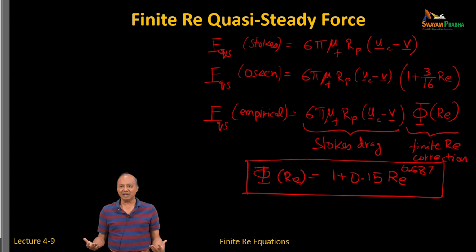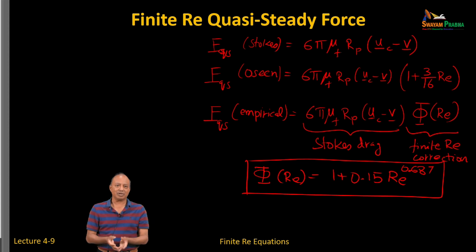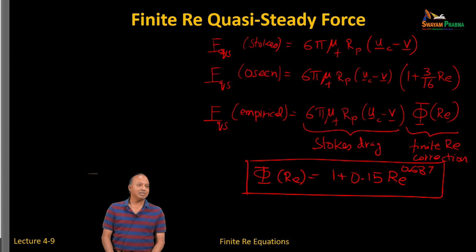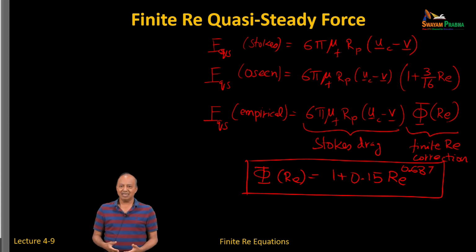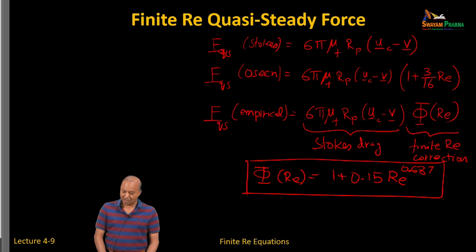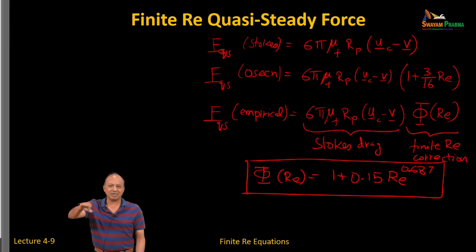You can do CFD, microscale simulations, particle-resolved simulations at finite Reynolds numbers. You can use OpenFOAM, Fluent, whatever you want, and you get the drag as a function of time, divided by the Stokes drag, and whatever is left behind is the correction. And this is one good formula. I use it all the time. It's very efficient. But this formula is good for Reynolds numbers up to 20,000, 30,000 like that, and afterwards you all know that it reaches a constant value after a while.